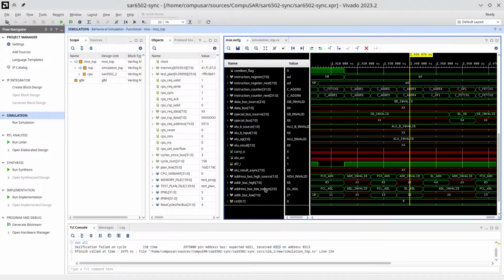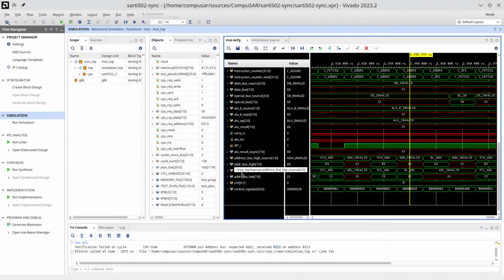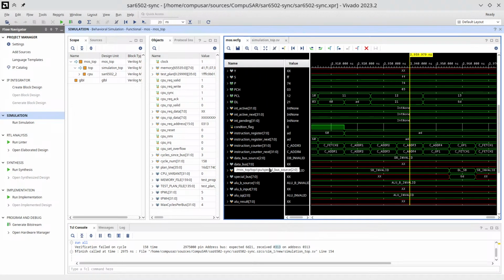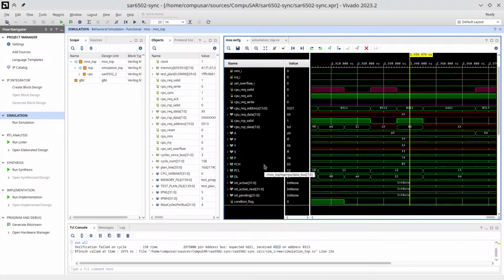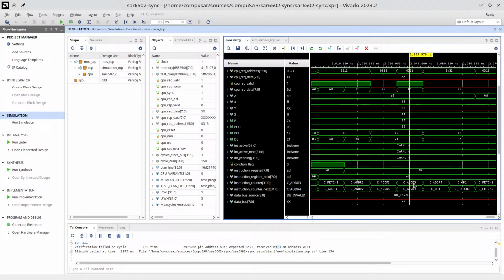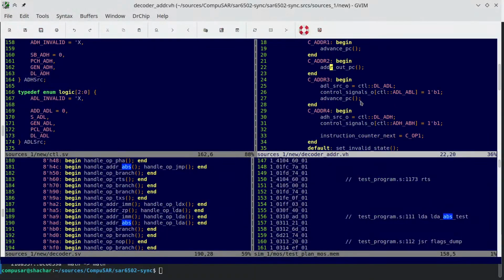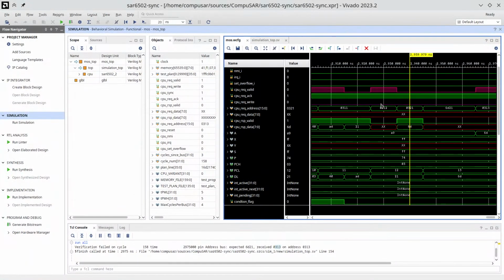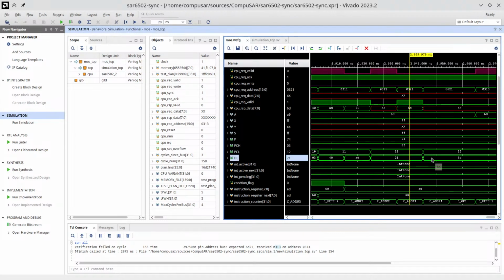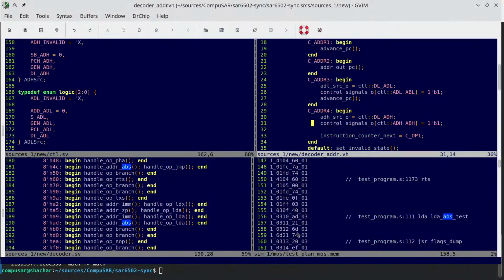And we're doing what we expect with it. So we're putting it on address bus low, and we are loading it into request address low. Okay, we're not outputting a request, but we did update the latch for the address bus. So that's address bus ADDR3. On ADDR4, we got the reply to this read from 0312. So DL now contains 6D, which is what it should.